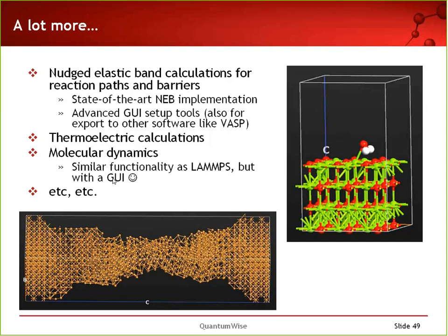Now, when you take a nanostructure, you take an indium arsenide fin, which is just 8 nanometers across, for instance. Actually, it turns out that the subbands have, first of all, very different effective masses. They have very anisotropic masses, and they're very highly non-parabolic as well. So there are some challenges in this area. We are actually working with some TCAD companies to try to address that, but I don't have an example at the moment. I could show you band structures of these fins, and you can see how non-parabolic they are. But this integration with the TCAD tools, I would say that's a very active work in progress right now, but we don't have any results yet.